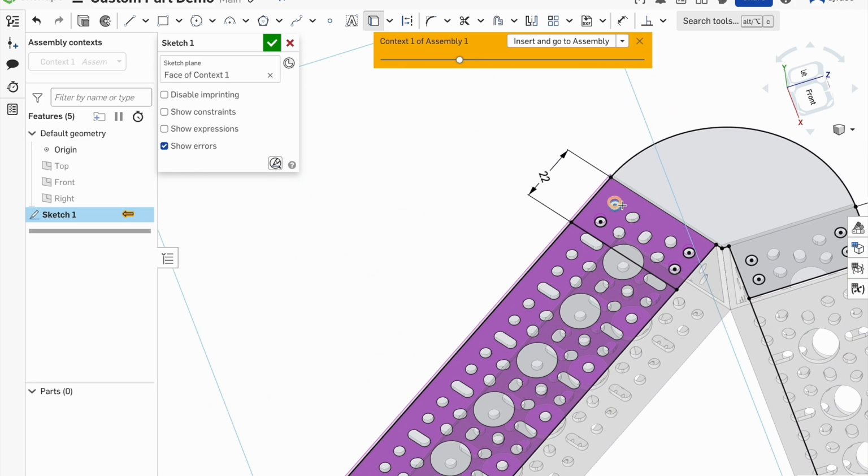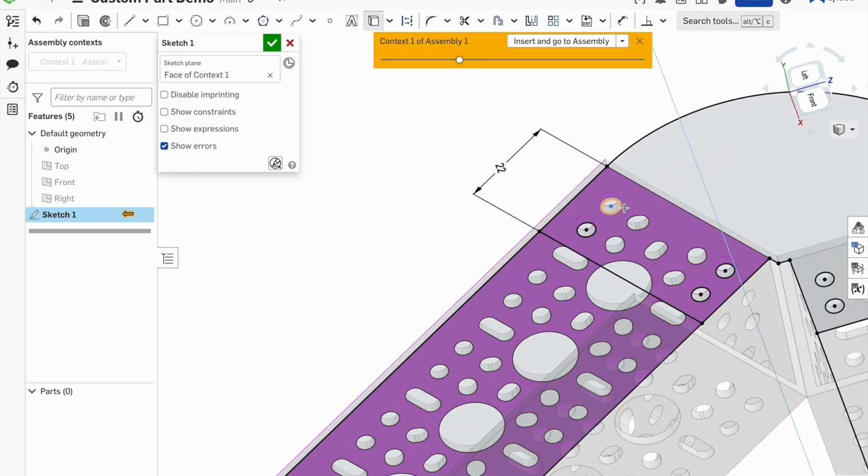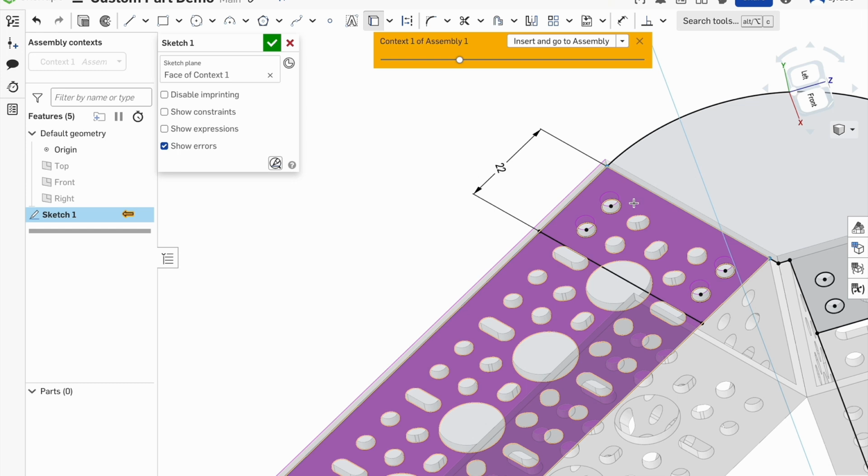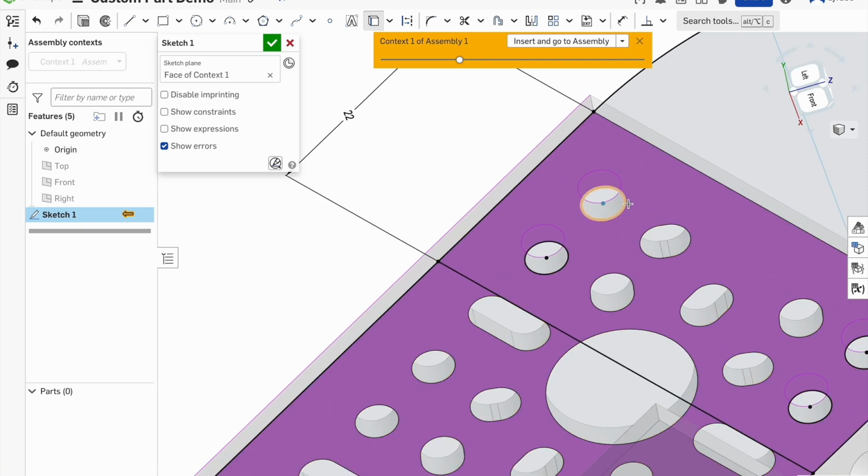However, if we 3D print a hole with the exact same diameter as the metal U-channel, the hole will be pretty loose and the screw might strip the threads pretty easily within the part itself. So we want to create the plastic hole a little bit smaller so the screw has something to grip and form threads inside. The diameter of the goBILDA holes is 4 millimeters. So I like to do 3.5.